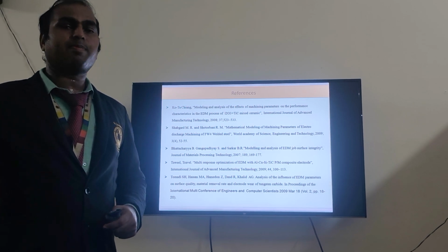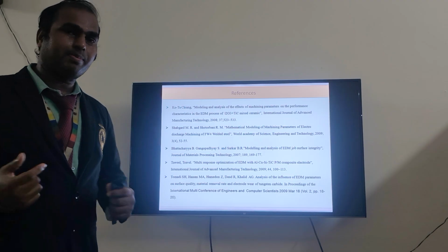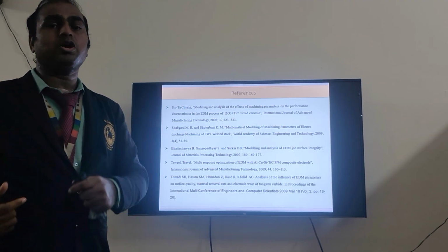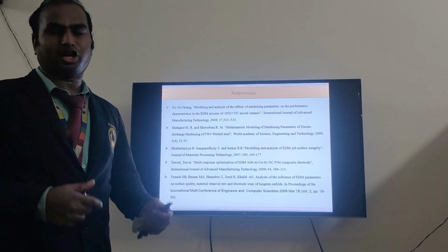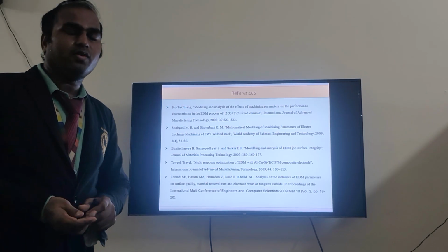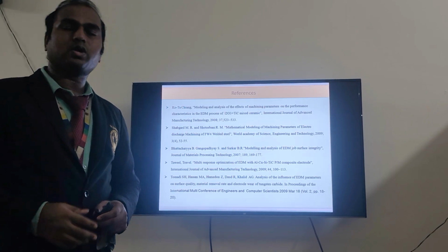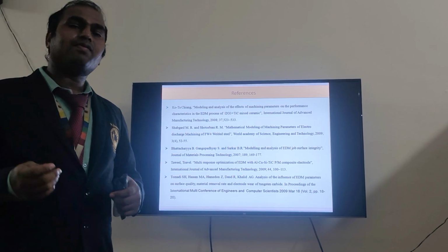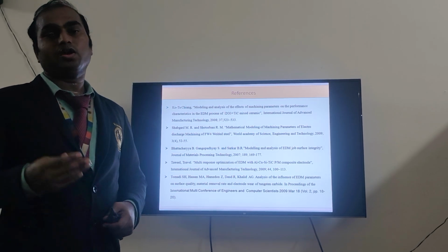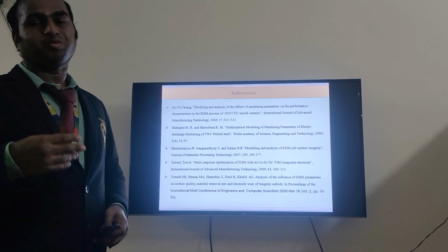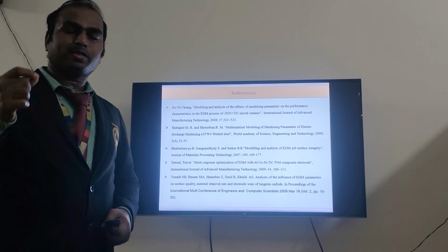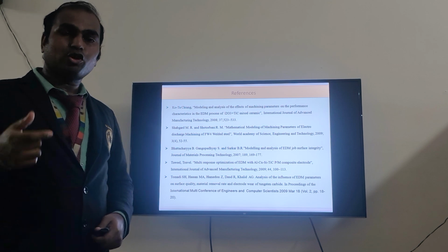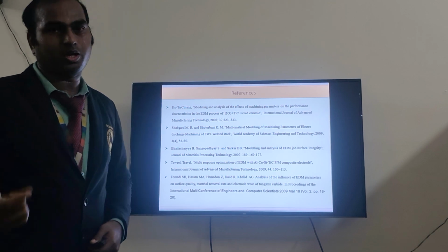In upcoming research, the additively manufactured tool will be taken forward for special treatment such as cryogenic treatment. This cryogenic tool will be dipped in liquid nitrogen for 12, 36 and 48 hours. After that, in the same way, we can do many case studies, knowing that the newly developed tool on the EDM shows better performance in the unconventional machining process.